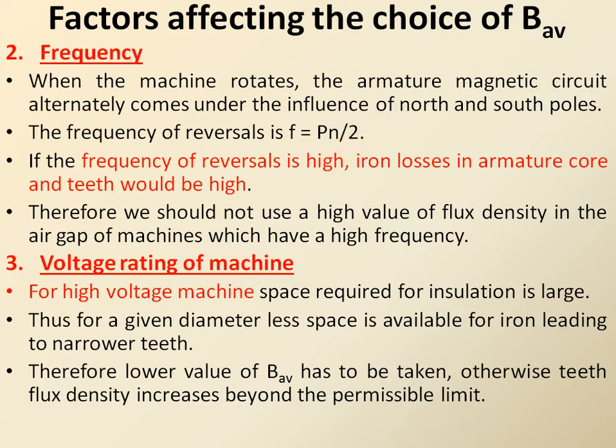As you have studied in your machines course, the iron loss, which is the hysteresis loss and eddy current loss, depends on the frequency. So if you choose a very large value of frequency of magnetic reversals, then definitely the magnitude of iron loss will also be very high. Therefore, we must ensure that a large value of specific magnetic loading should not be used in the case of machines with a large frequency of magnetic reversals.